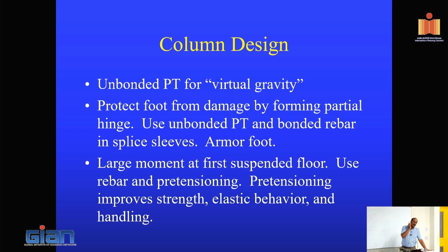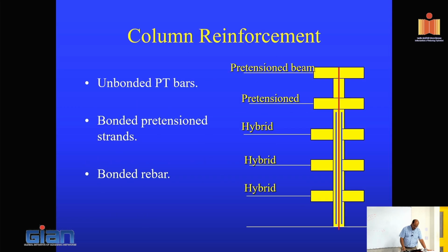So, to create a pin connection for gravity columns, this is what we did. We basically took the gravity column. This was not necessary, but we ran a post-tensioning tendon all the way at the center so that it will have small moment resistance, but it can do this elastic behavior, and it can also provide the pin support that we are looking for with a pretty reduced amount of moment resistance at the base.